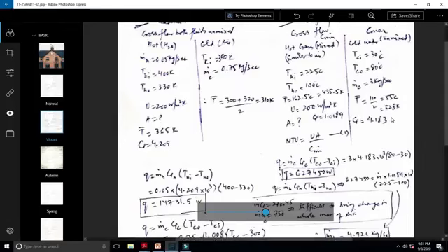Cp is 4.183 kilojoules per kg per Kelvin. So we will put that value of Cp over here along with the mass flow rate, which is given to us as 3 kilograms per second, times delta T, and we get Q as 627,450 watts.